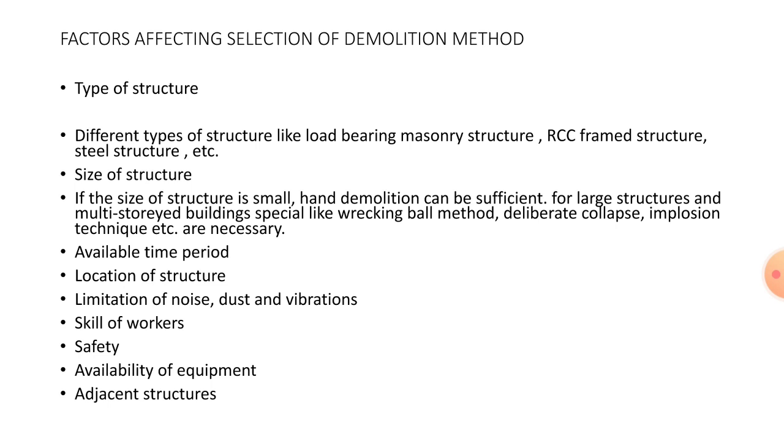Then the available time period, what time slot is given to us for demolition of the building, that should be known. Location of structure, where it is situated, that should be known. Limitation of noise, dust and vibrations.